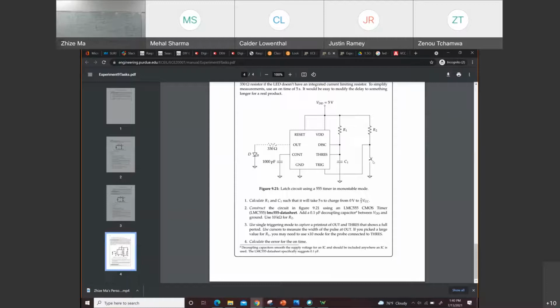So you can just mimic this function by plugging the jumper in and plugging it out. That's like a switch. So you can connect a jumper from R2, from this node, to ground, and then disconnect it by yourself. You manually make a switch.